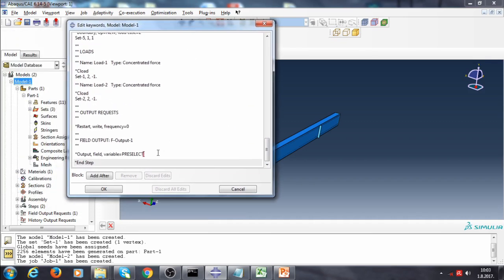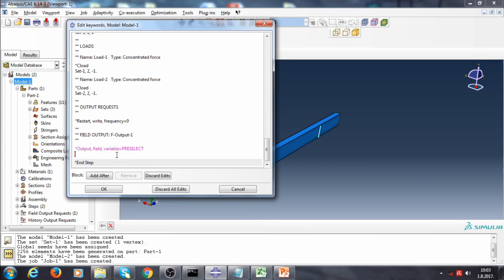So click here, click enter, and type in the following: node file u. What this does is create one file with the information regarding the eigenmodes, so we can later call upon that file to include the imperfections in our model.